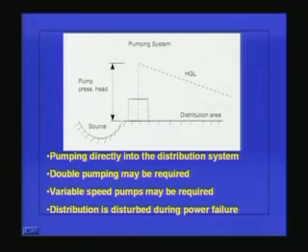Here the water is pumped directly into the distribution system, and what you see here is a pump and pressure head, and then in the distribution system you will have the drooping energy grade line or the hydraulic grade line. Now, whatever is the elevation of the energy grade line or the hydraulic grade line at the tail end of this distribution area, that should be more than adequate.